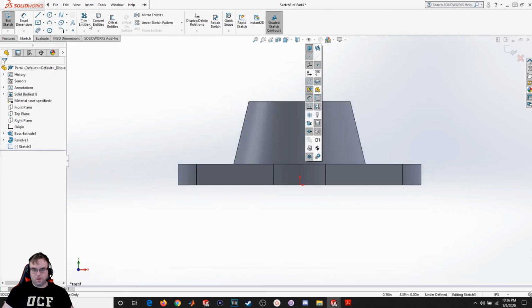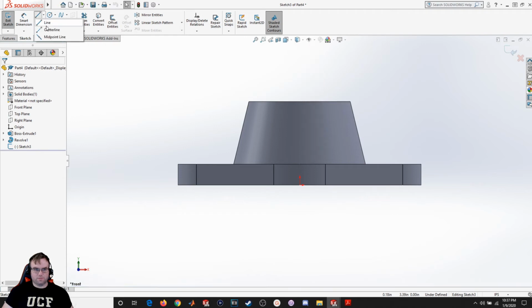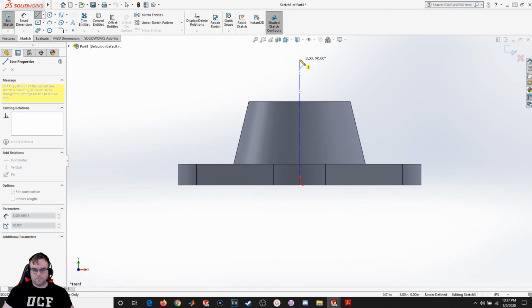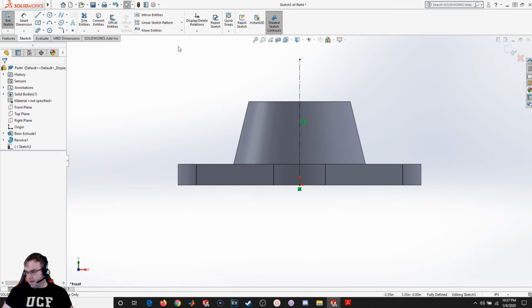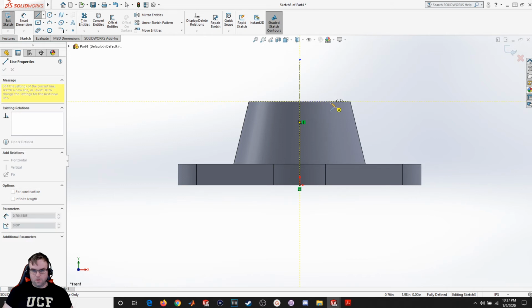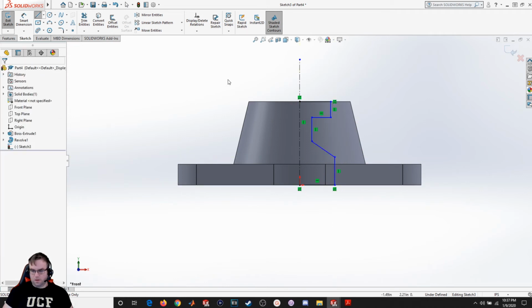And I'm going to give it a line of revolution. Okay, and now I'm going to just do a basic sketch of it. So I'm going to go over, down, over, down, over, down, and close it. Alright, so now to give it some dimension, let's take a look.